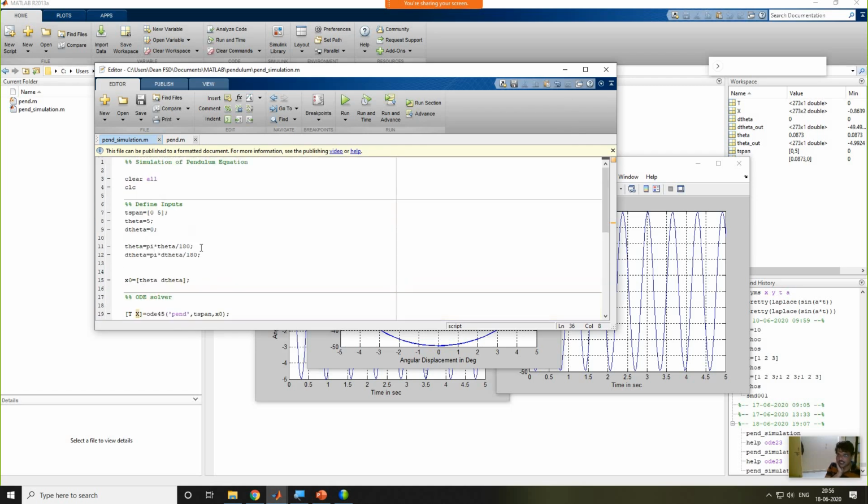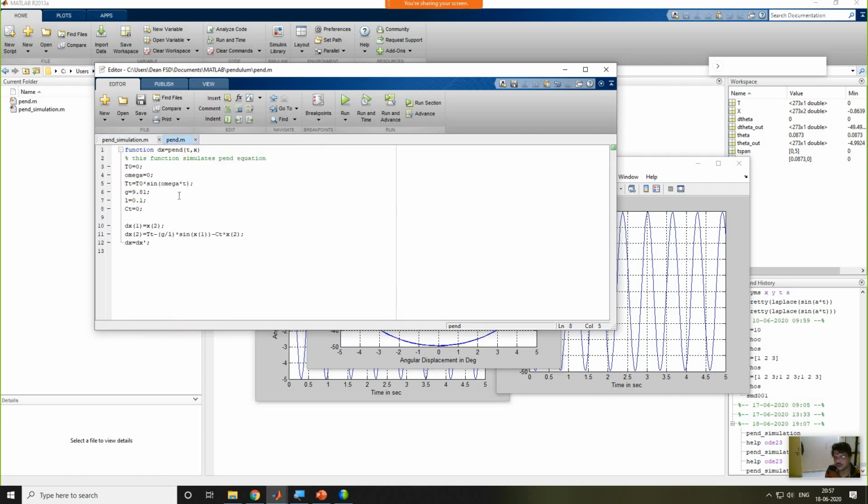So this is a simple pendulum without any forcing function. We'll now look at how to simulate the forcing function. Here I will keep the damping at somewhere around one. I prefer lower damping because I can observe more of the transient response. I'll provide 10 as the forcing function, then an amplitude of 5, and a frequency of maybe 10 omega, that is 10 radians per second.